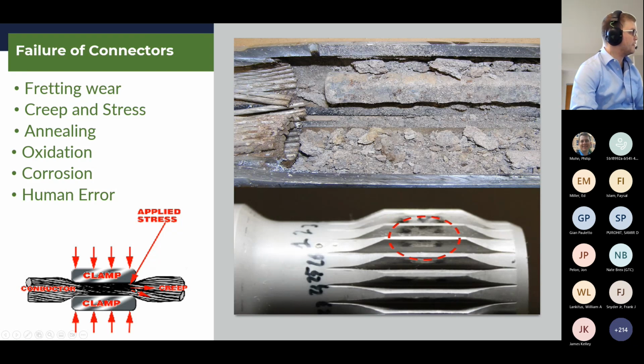In this picture in the bottom left, it shows when you use clamping methods that at points of stress, material may clamp, creep, and elongate, which will cause failure. And as the conductor starts to heat, you're getting a similarity to the annealing process, where essentially you're heating up a conductor past its recrystallization point.